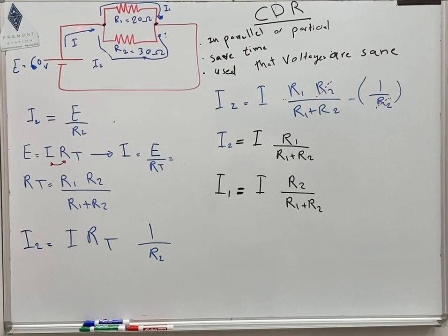That makes them parallel. And this is just showing the current in this circuit and its direction. It goes like I2 through R2 and I1 going through R1. And this is the rest of the circuit. So this wire, like we know, and these resistors consume electricity. And this is the source, which is a battery, because it's DC. So what's I2? I2 is VR2 divided by R2.